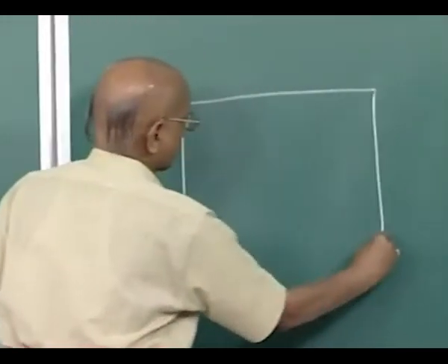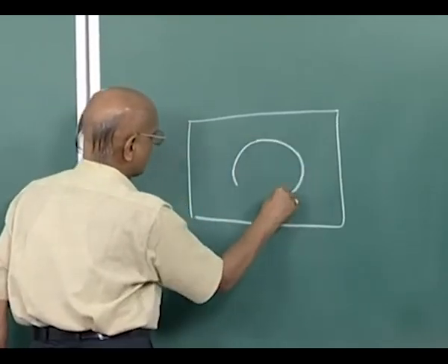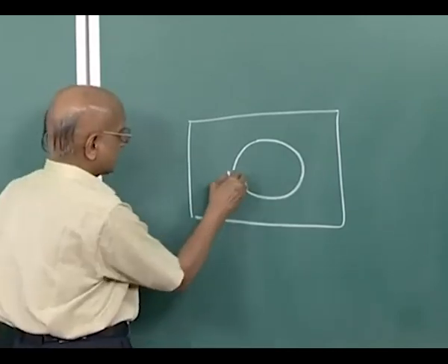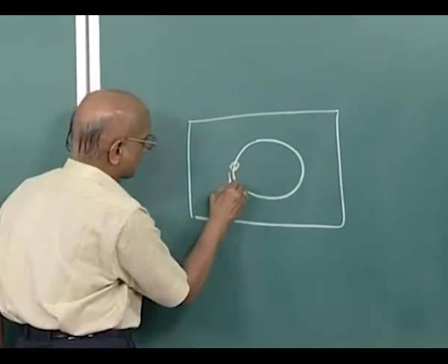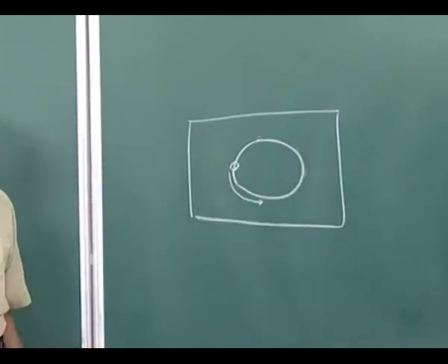kinds of holes. However, you can also move the workpiece table if there is a large hole to be made, just like if you want to do the trepanning operation where large movement of the workpiece is important. As I show you here, suppose this is the workpiece and you want to make a large size hole which may be of a few millimeters. Then you move the table such that the beam is always hitting on the periphery from where you want to remove the whole of the material.